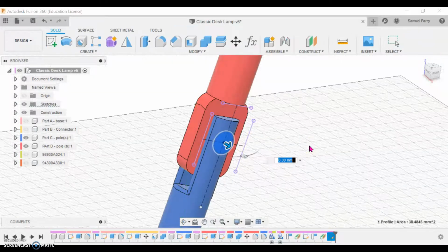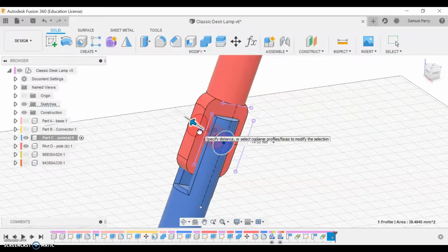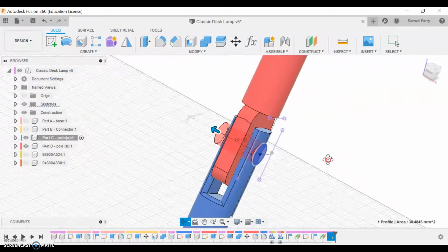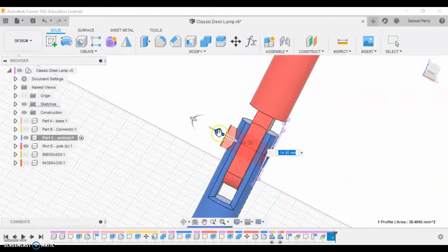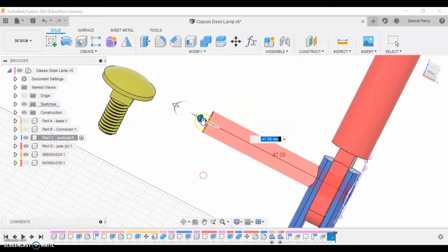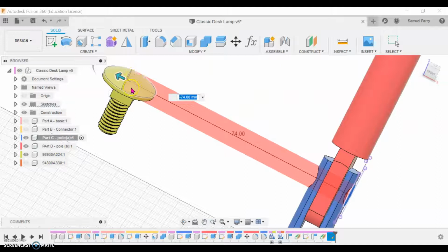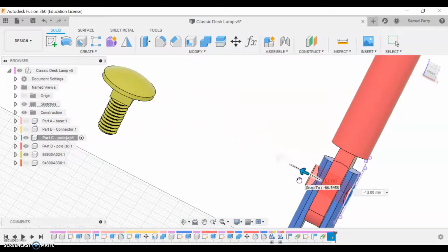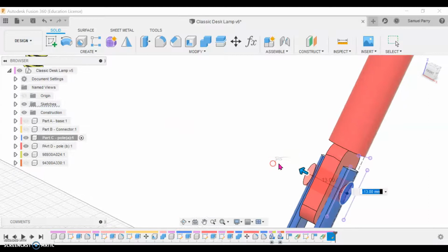We'll press the E button for extrude. We're going to push it through the other side. I'm going to just manipulate the view so I can see that it's gone all the way through. Some students really exaggerate this. However, it's risky because if you've got components over here that are visible, for example, if I bring that there, it will actually cut into that component. Okay, so it's important to make sure you've cleared the component you want for making the hole, but don't exaggerate it any more than needed.